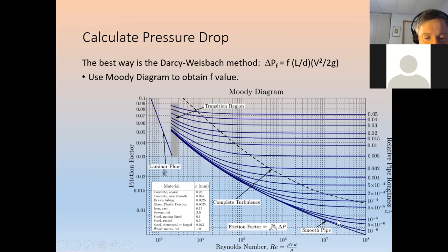And this bottom curve here where it says smooth pipe, see, it goes right up here. That's the bottom one. You get these really low friction rates. And the friction rate goes up as the pipe gets rougher. But you can still see it's very low compared to the laminar friction layer. And that's because if you look at that cross-section of pipe flow, I had another slide, fully developed flow, the section of turbulent is bigger, while the high velocity component is bigger than the laminar.